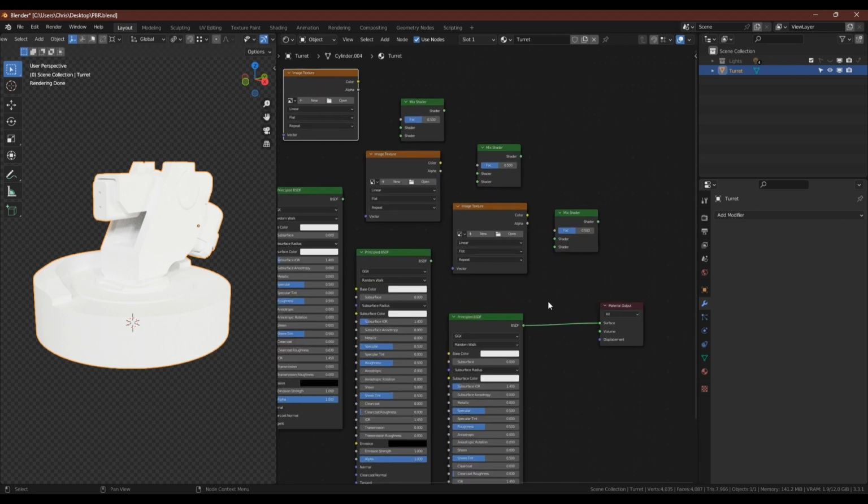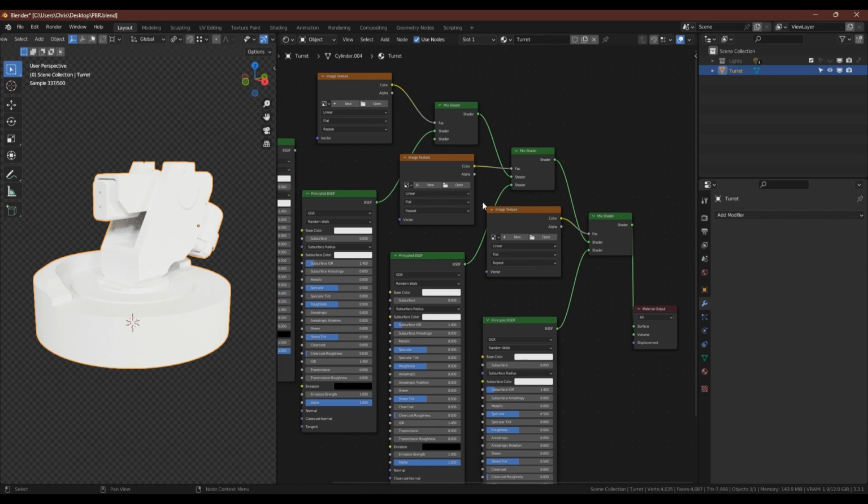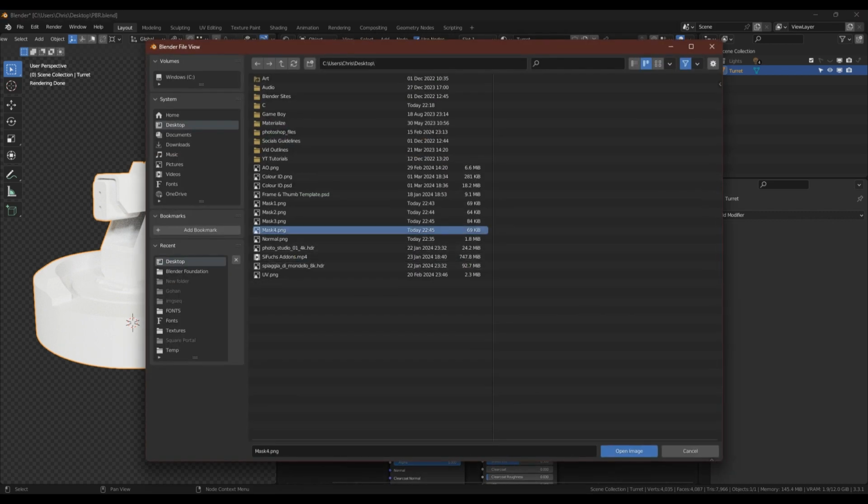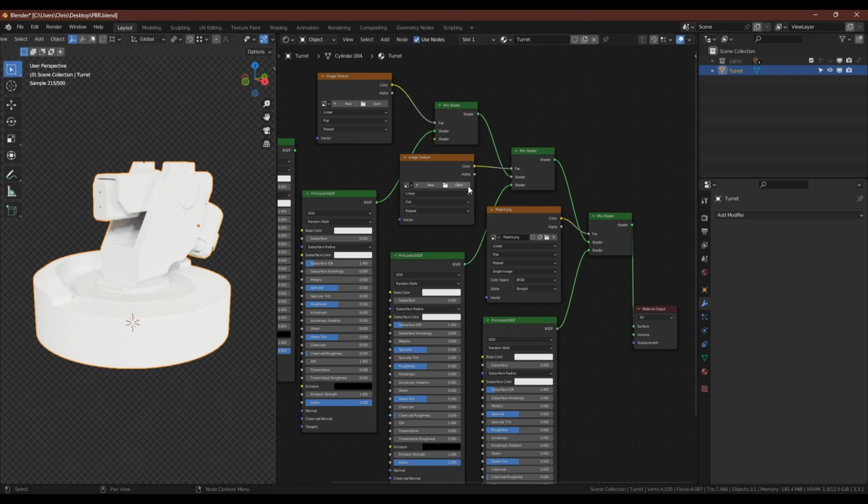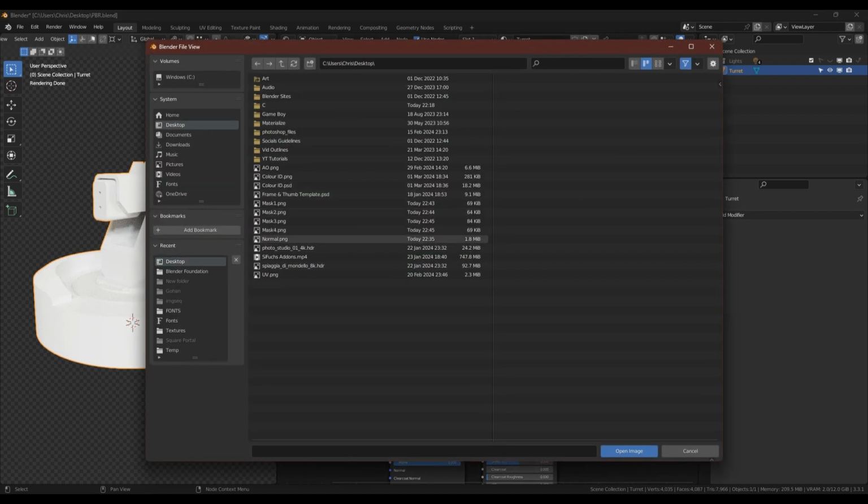It can be slightly confusing the way you link these up, so if you just try and copy what I do on screen, you'll note as well that we do actually have 4 masks, and that's because one of them we'll also use for the metal. So although we've got 4 materials, we only need 3 masks for those. But we've kept the other one anyway because 2 parts of this model are metal, and we can just combine those rather than baking out a metal map. It's much easier to just combine 2 maps in, say, Photoshop than worrying about baking a map out that's just black and white data.